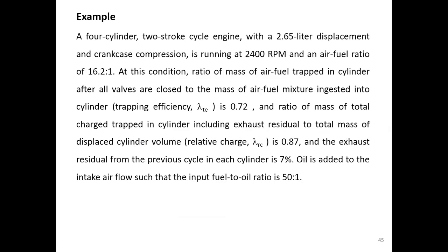The first one is the mass of the total charge trapped in the cylinder, which is the first mass that we talked about. But remember, inside the cylinder we also have the exhaust residual, because the exhaust gas does not completely fall out of our cylinder. We still have some of the exhaust left over in the cylinder.